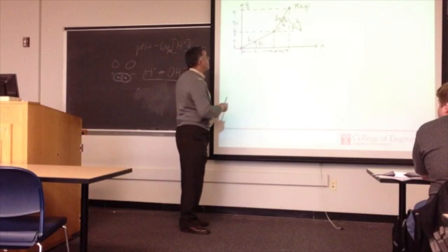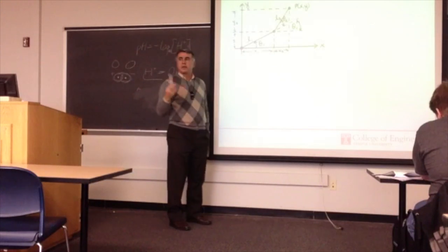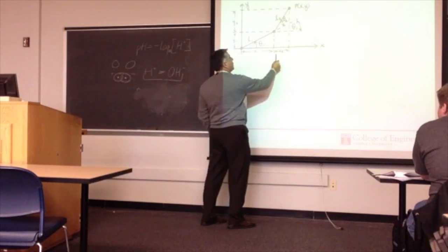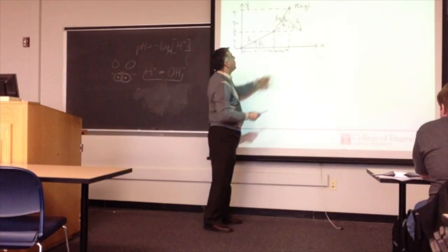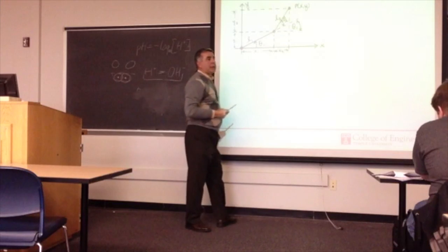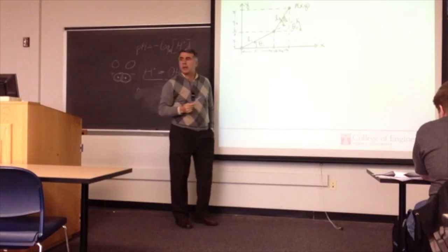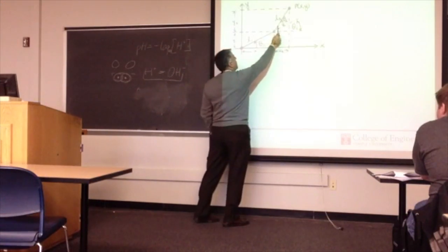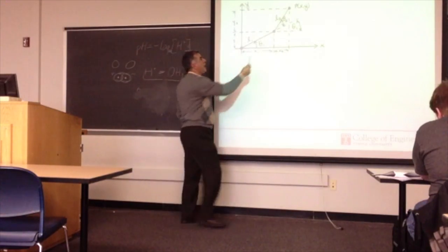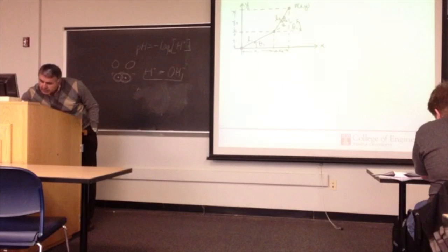What I said was x1 is simply L1 cos of theta 1. That part we understand, right? The part that is perhaps a little bit more complicated is x2. In order to find the x2, we should really look at this right angle triangle. And in this right angle triangle, in order to use the cosine law, we need to have that angle. But the only angle that we have is only theta 2. What we don't have is that little part here. Let me show you over here. This little part.